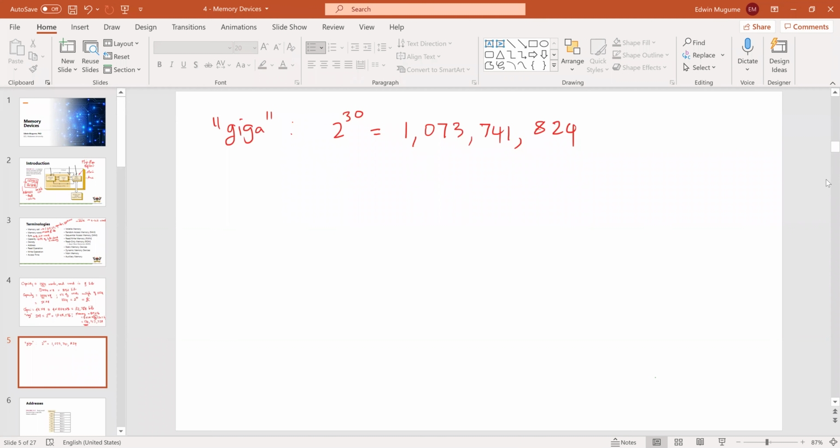So I can say that I'm looking at my capacity written as 4G times 4. This is the number of words, and we know that each word has 4 bits, and so you can continue with your calculation and find the capacity. So really the capacity is the size of the memory, and it is the number of bits that you're able to store. That's why you have flash drives of 4 GB, 2 GB, 16 GB, 32 GB.